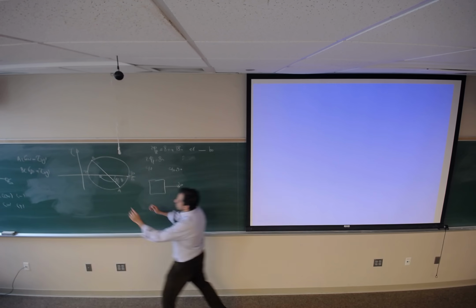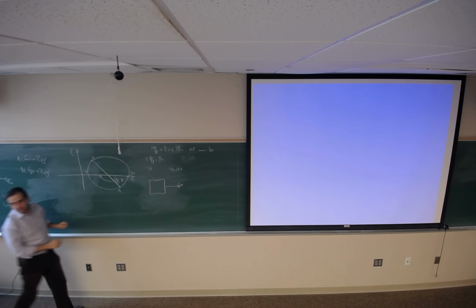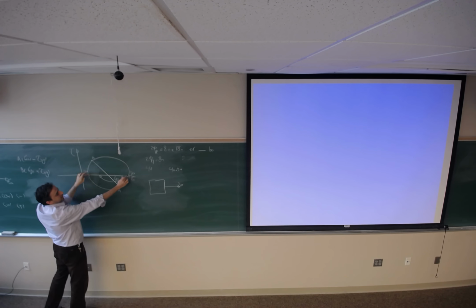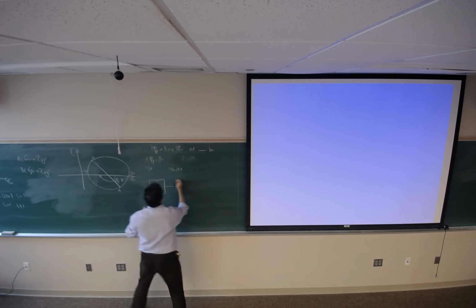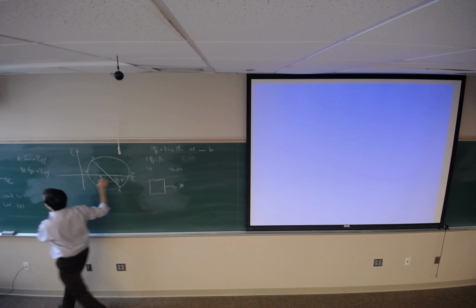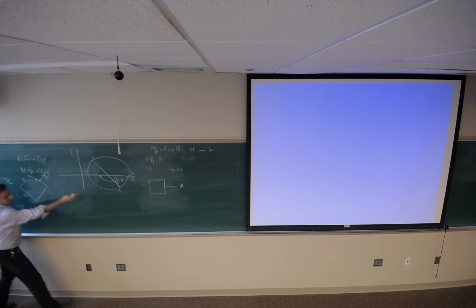You just look at point A and B. Where are they now? So if you rotate this AB by this angle, what is the value for stress at point A? It's going to be 110. How much did you rotate that? Half of AD, which is positive 40. So you rotate it by the angle of 40. So point A is going to be here, point B is going to be there, and A is going to see 110, if this is 110.